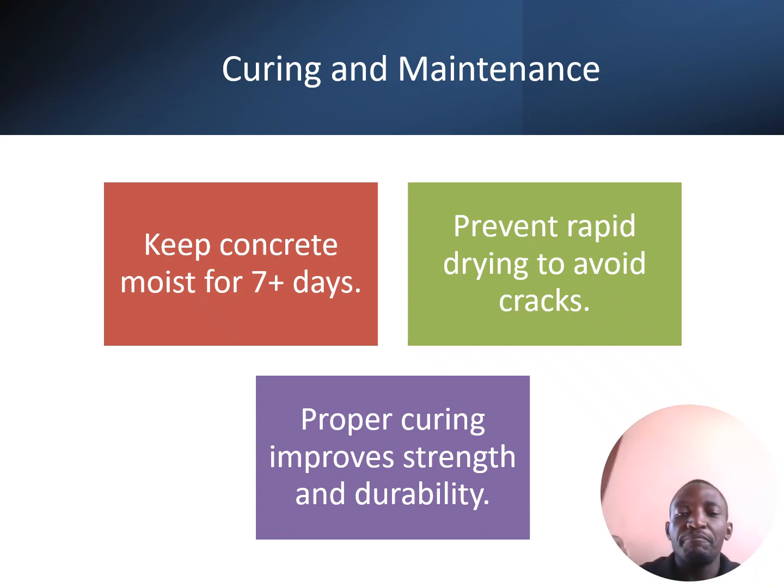You must prevent rapid drying to avoid cracks. Rapid drying causes cracks if the sun is too hot for a day. You must avoid the concrete drying rapidly. You must pour the water often so that you avoid cracks on the concrete.